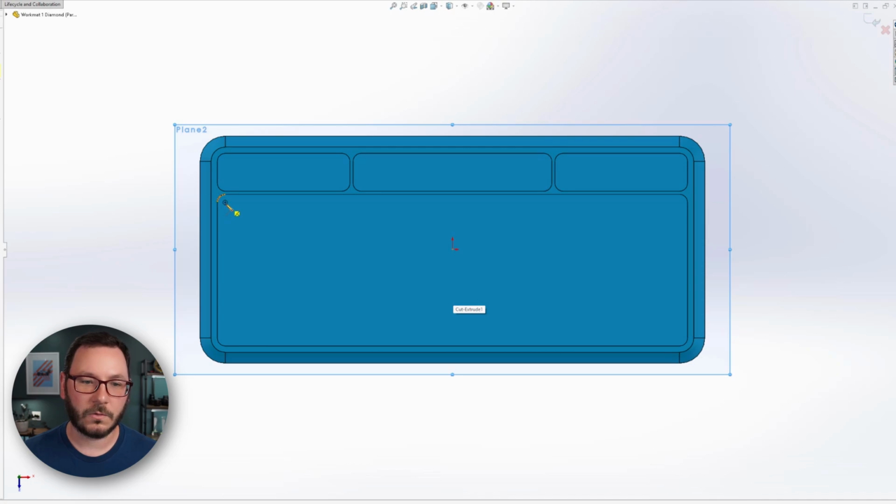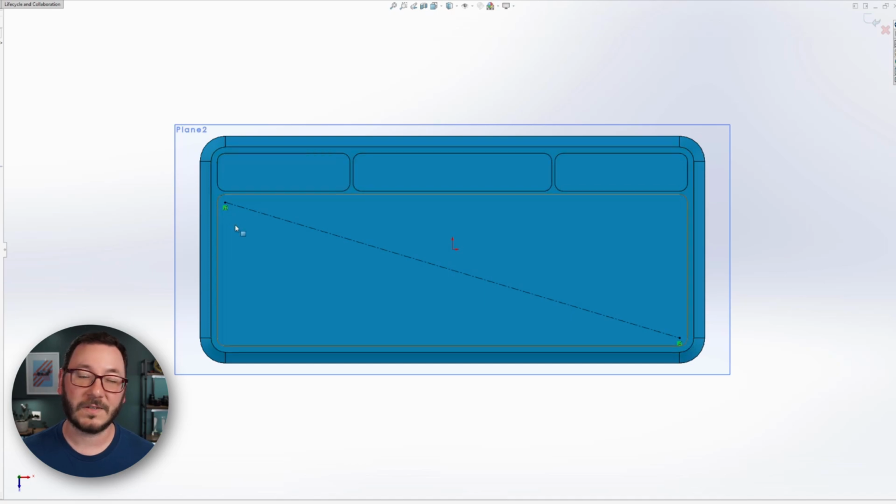Now, one thing that you'll want to consider when you're making geometry like this is you see that I have fillets already here on the corners of this geometry. So you know, this might not actually be the wisest thing to mark this off from fillet to fillet, because fillets are things that tend to disappear in designs down the road. So if you were to delete these, then we're going to run into issues with this. For the sake of example, I'll be okay just marking this off, but it certainly is something you'd want to consider.